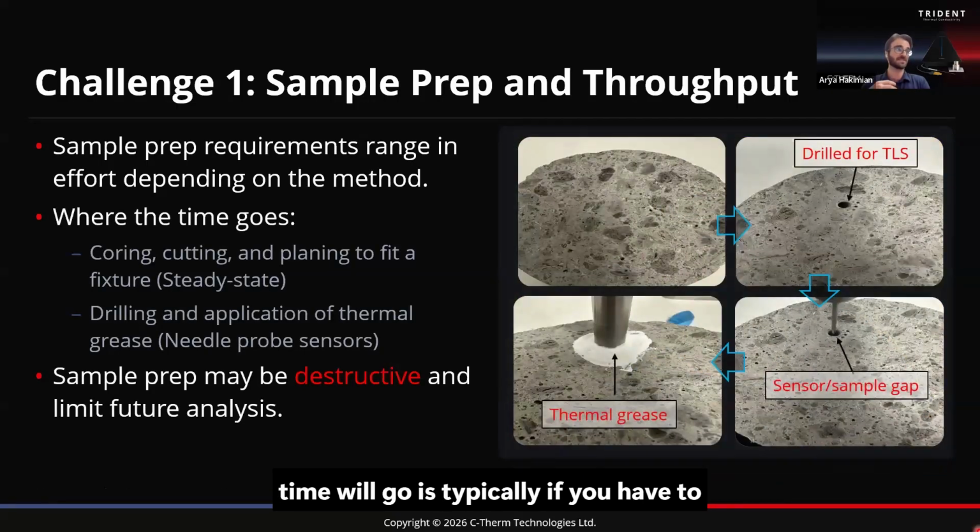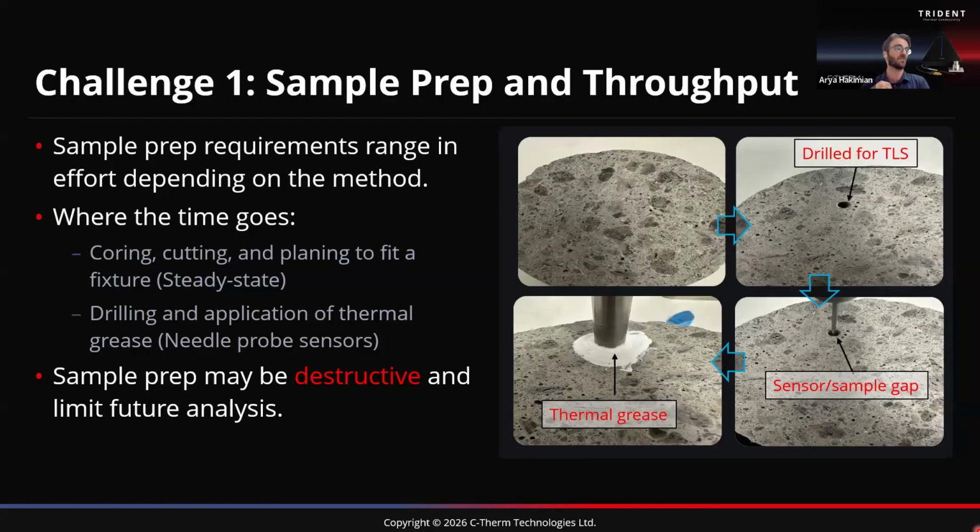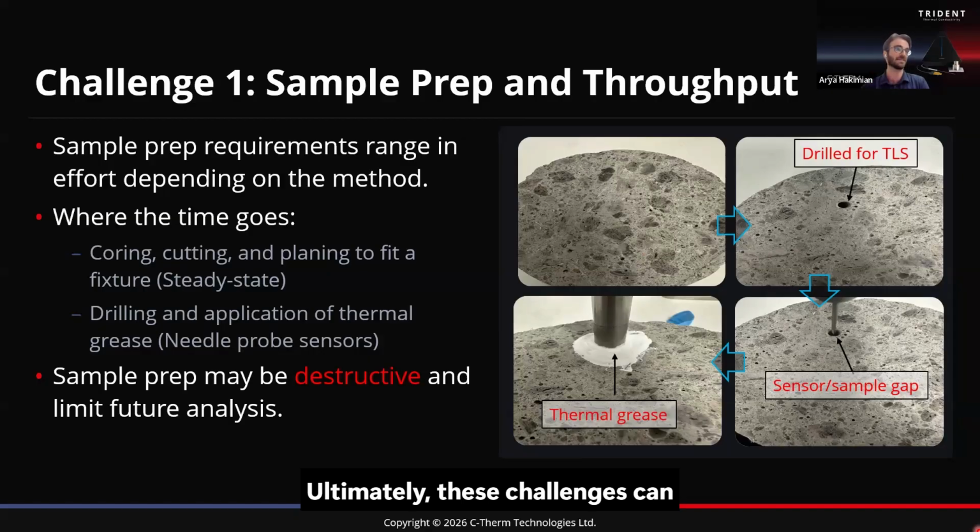So where the time will go is typically if you have to do any cutting or machining or planing, leveling of the samples, drilling. In the case of the image you can see on screen, for the use of a needle style sensor, having to drill the sample, apply thermal grease. Ultimately, these aspects introduce some challenges in how we get the samples ready as it relates to really your throughput capabilities. Also, note here that in some cases, the prep can be destructive in nature to the sample.